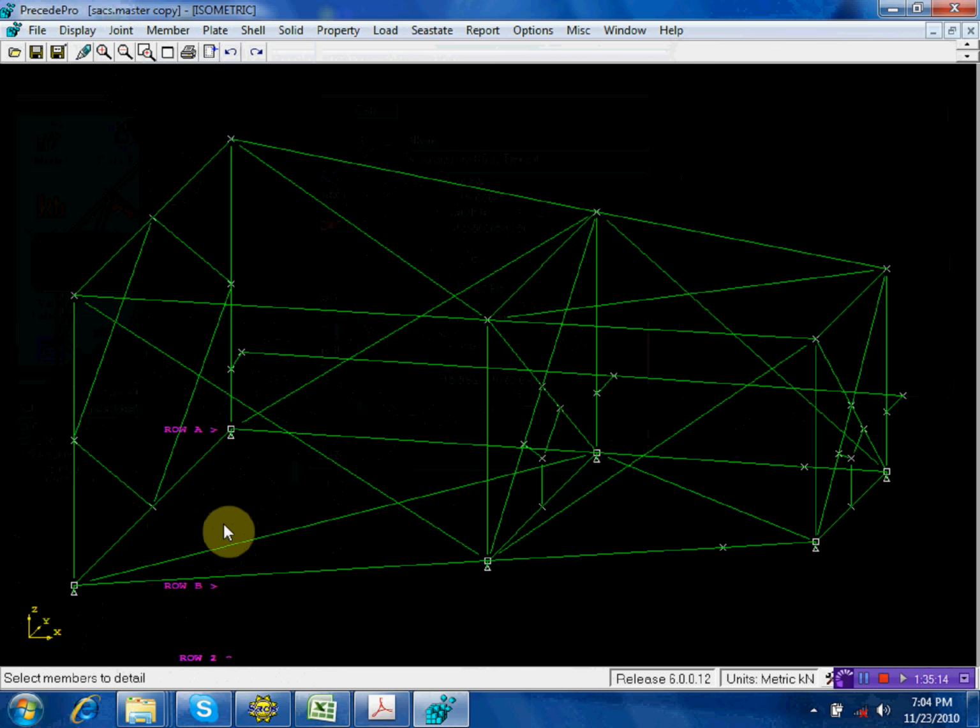It will be unstable. Why? Say the center of gravity is here. You remove the load here. The only support is this, and this one will be automatically cancelled by the program because this is compression. So if you put no load here and no load here, it will be unstable. At the same time, it will not be realistic. Why? When you skid it, there's already a barge, unlike you remove the barge and then you skid. So that's impossible. So we'll consider only support deflection here or no load here and no load on the other side.